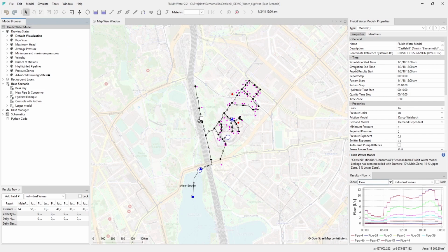Usually in common planning situations, users simulate at least 2 days, but take results only from the later day. This lets you ignore the very first time steps of the simulation, which are usually more unstable, and also otherwise lets your model behavior settle from its initial conditions.